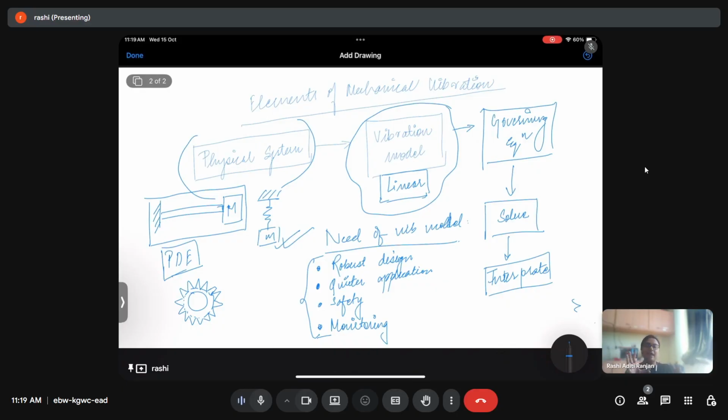After this, we apply that algorithm to the continuous monitoring of our system. So as soon as the algorithm detects that there is a change of vibration data and it matches with some of the fault A, B, C or D conditions, only then the operation of the machine is going to stop, to avoid any kind of catastrophic failure.